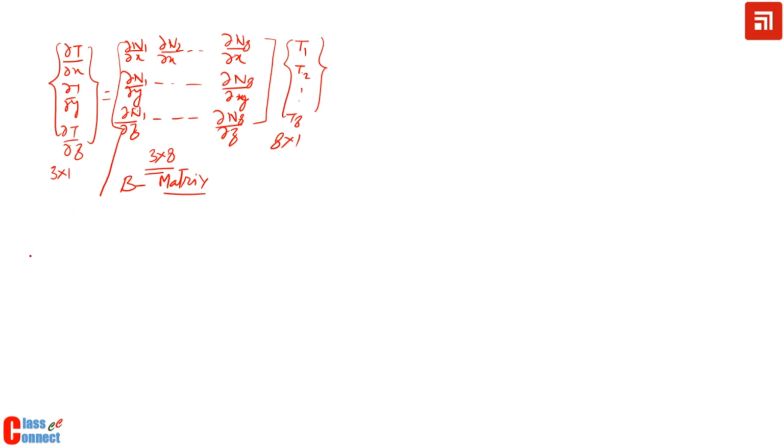We can also write the first part of that integral that was given by del n I del x, del n I del y, del n I del z. So these are again where I is from 1 to n, that is the number of nodes per element.